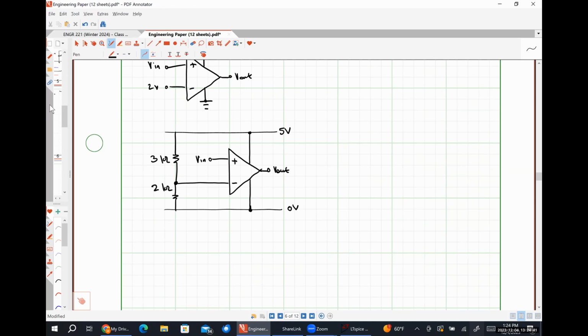But now we have this thing in series. These two are in series. They can be combined. They're just in series with whatever that is. So when you have three identical resistors, it's actually just the resistance divided by 3 to go from a delta configuration to a Y configuration.